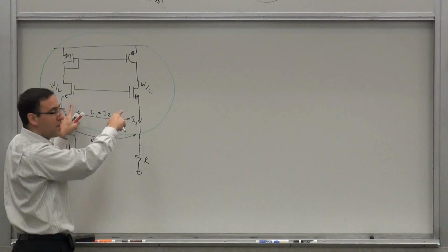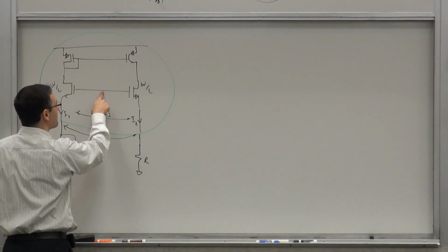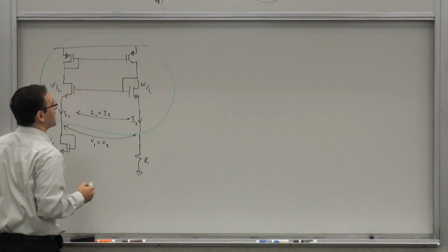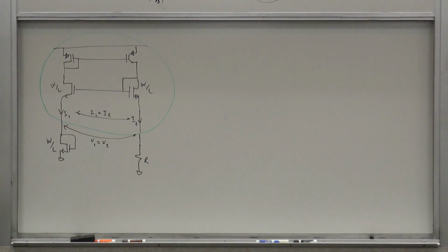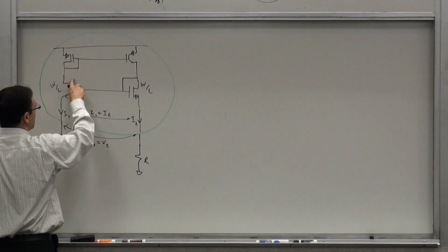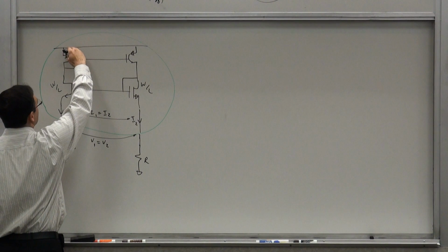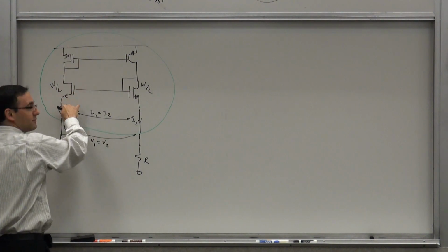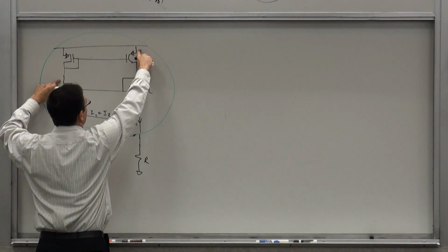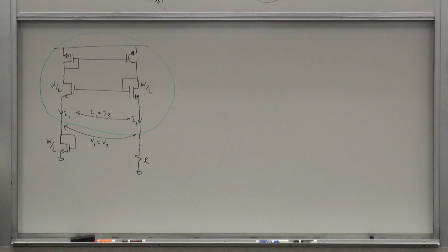Correct? Now, this of course has a little problem because this is floating in the air. There's nowhere it comes from. So I have to make this something like that. And it has to be on the opposite side of that, otherwise I will have two diodes in series, which basically says this voltage will be determined by the supply. We have supply dependence. But then once I click on the other side, the variations will be absorbed here if the supply is changing.